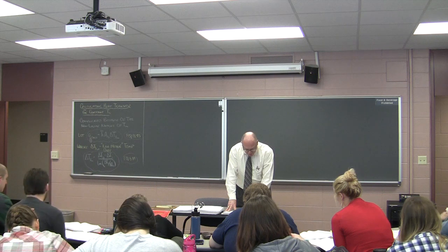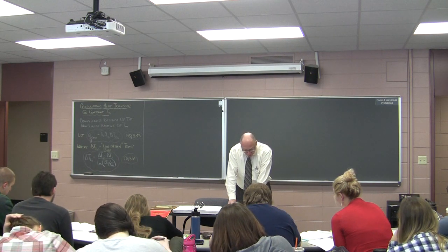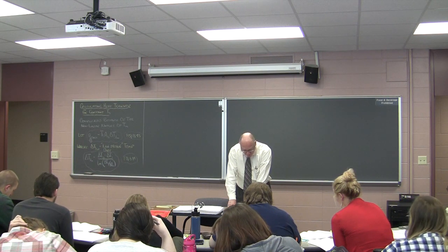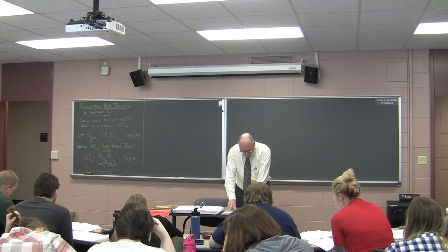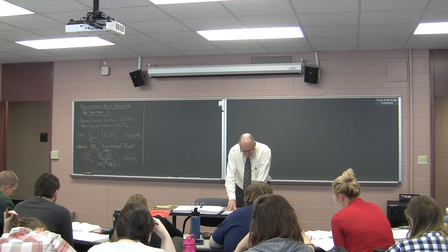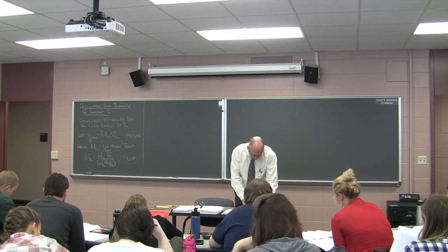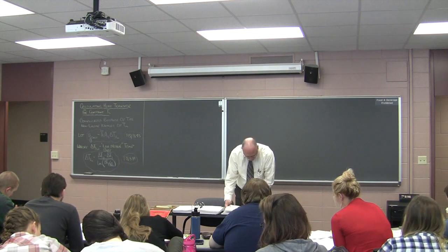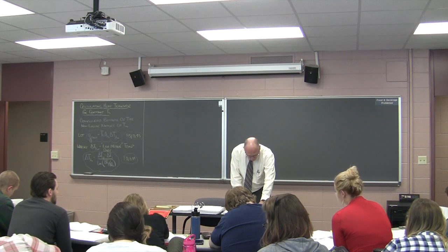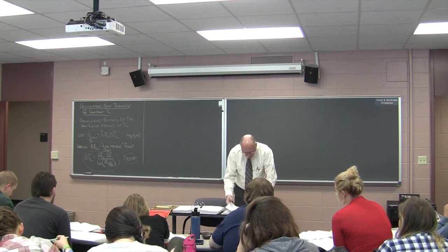And for these two equations, look at the conditions in 8.57: laminar flow, thermal entry length, or combined entry, with a Prandtl number of greater than 5, a uniform temperature at the surface, and then this Graetz number. I forget the name of it, but it's just a combination of the Reynolds and the Prandtl number.